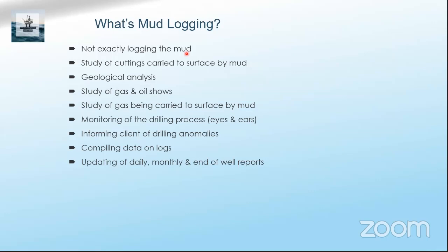So why do we call it mud logging? Whatever data acquisition, whatever information the mud loggers get, is with a medium, using the drilling fluid, that is mud. As I mentioned earlier, there are no tools or sensors downhole, unlike LWD or wireline. Logging is nothing but the continuous recording of data. In the case of wireline, we use wireline, that is why we call it wireline logging. In the case of surface logging, we use the drilling fluid, that is mud. That is why it is called mud logging. I hope everybody is clear, those who have not been very clear with this concept.